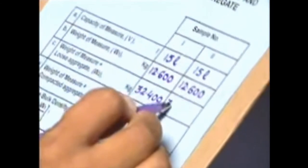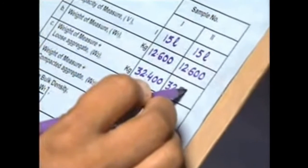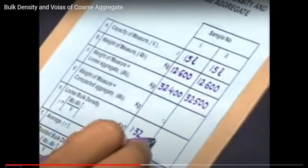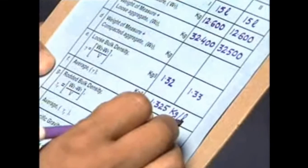Take another set of readings and record it in the observation sheet. The average of 2 readings is taken as the final value. In this case, the average value of loose bulk density is 1.325 kilogram per liter.